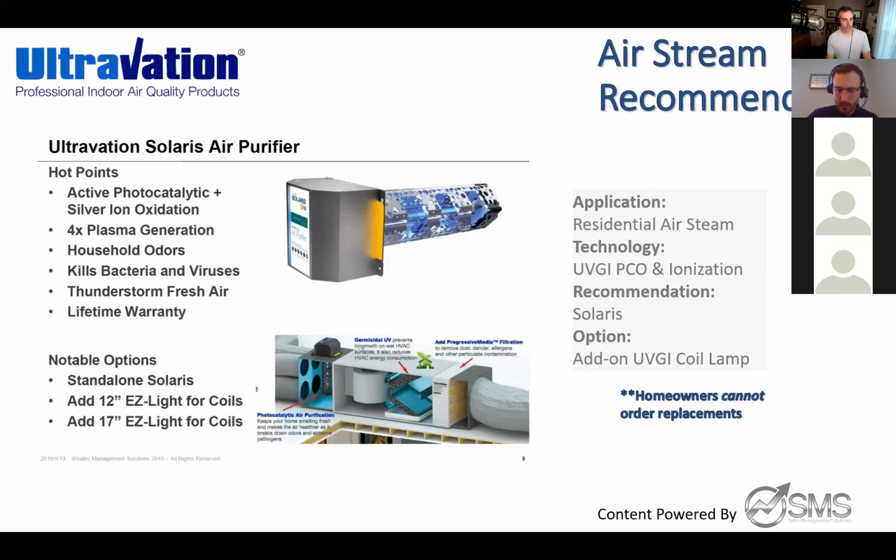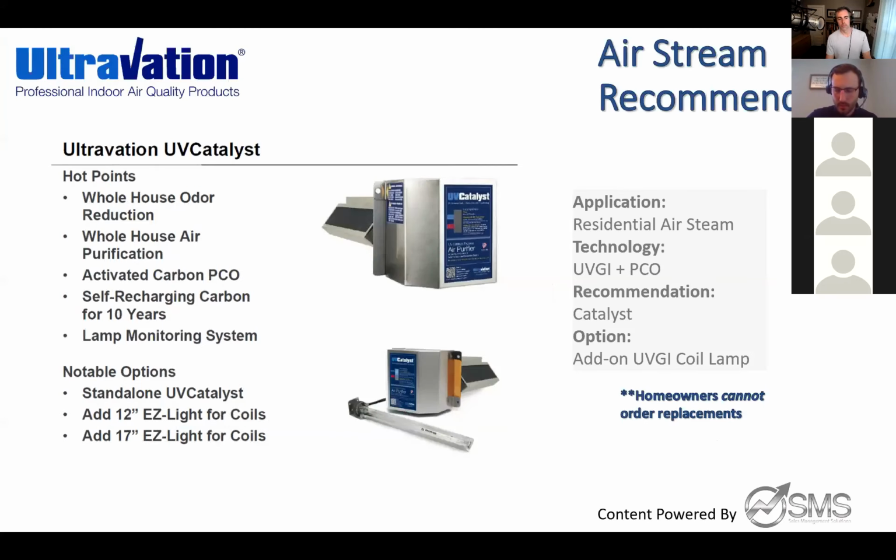I have a question. When you have to service it or remove it once it's expanded, how does that happen? You don't have to service it. I should clarify that. The only thing you're taking off is the power head, and then you have 2 screws that have the bulb mounted in it. So you just take the 2 screws and pull the whole bulb out. This whole apparatus stays installed in the ductwork.